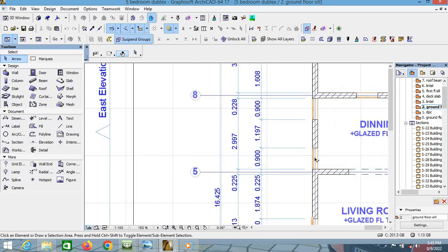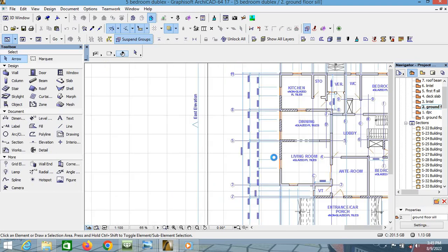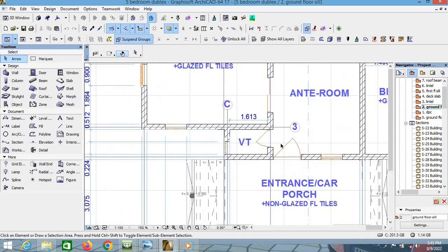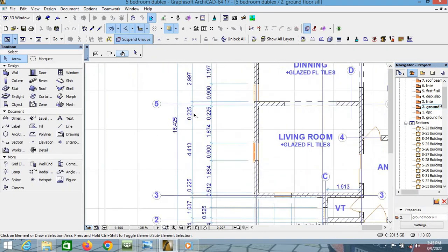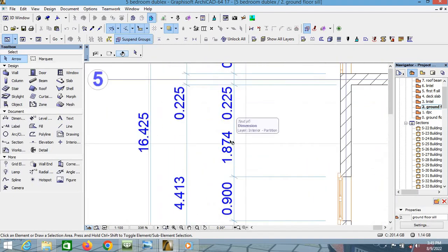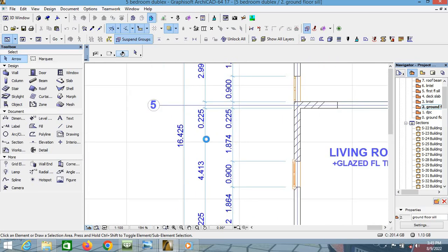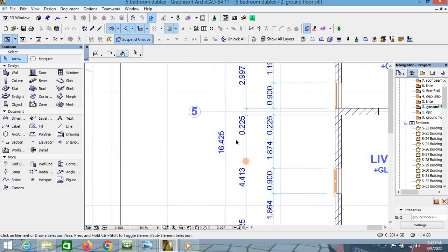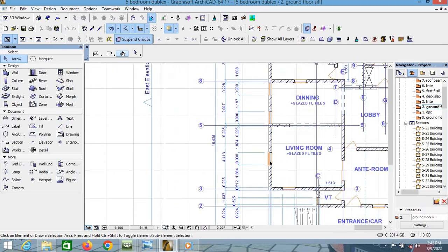What I mean by component is majorly the window to window spacings, or door to window. I had my first layer indicating majorly the window or door to window positionings or distance. Then my second layer is majorly for the wall to wall dimensioning. If you want to take your dimensioning based on the windows, you take a look at the first layer.